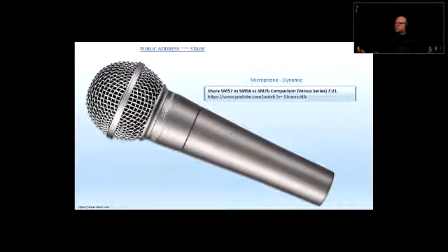One of them, SM58, is being used for stage vocals. Right? SM57 is the best microphone to use for stage instruments like a guitar. Sometimes it's a common practice, instead of connecting the guitar straight to the mixing board, people have their own stage guitar amplifiers that have speakers on them. You just place this microphone in front of the speaker of the amplifier. It's a very common practice as well.